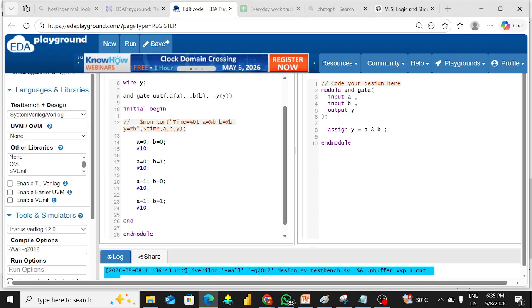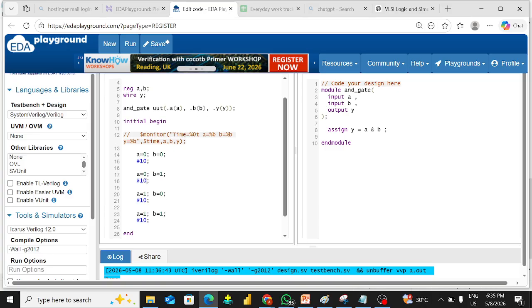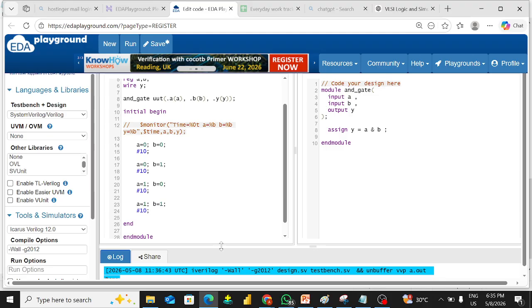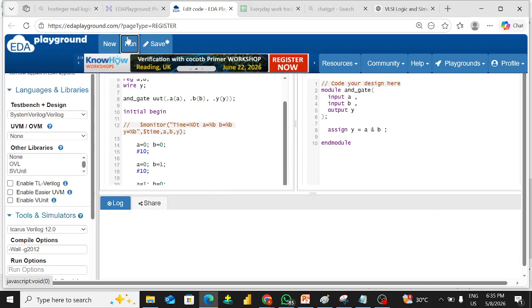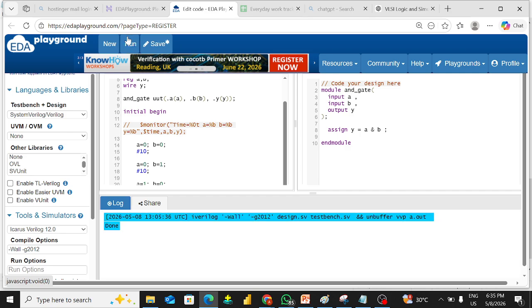So now I have completed my test input values, so I am ending those values. Now I am going to end that hardware block. How do you end that hardware block? You should mention end module to end that hardware block. Now see, if you run this code, what is it showing? Done. Every test case passed and was tested, and every test case was correct.